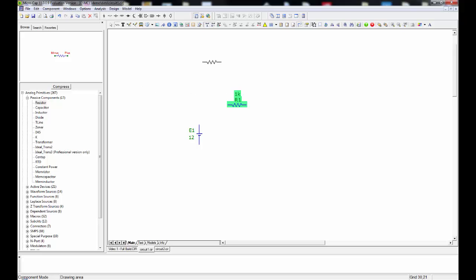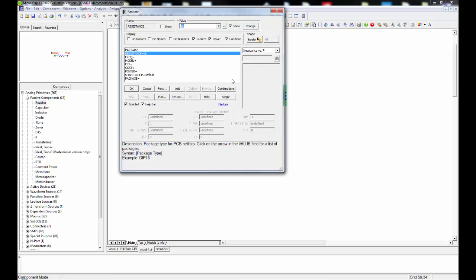And there's the resistor. Now by default the simulator assumes you want another resistor, so straight away you have one on your cursor. So move the cursor around. I'm not touching any buttons at the moment. So why don't I left click, right click, and I've got it oriented the way I want. It also assumes you want the same value as last time, which in this case you do.